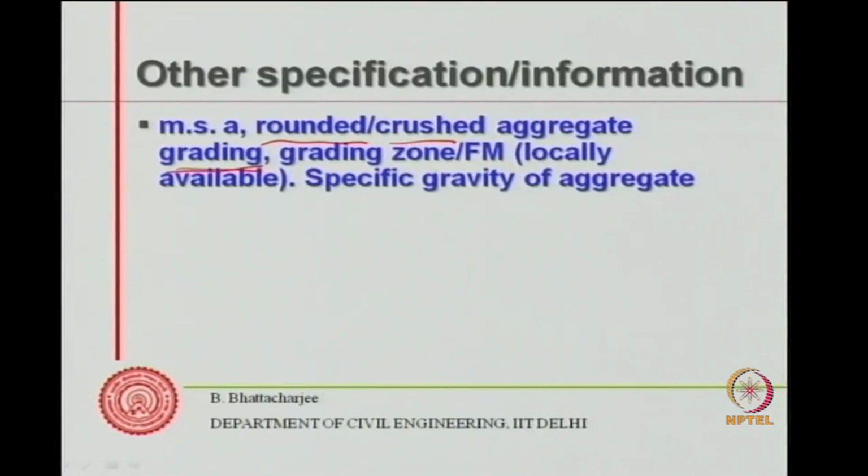Similarly, for sand, the grading zones may be important. Again, that's telling us what is the size fraction, the proportion belonging to each size fraction. Fineness modulus, also we have discussed sometime earlier, is again a kind of measure of an average size. So size of the aggregate, their packing characteristics, are governed by shape of the aggregate, maximum size of aggregate, and proportion in each size.